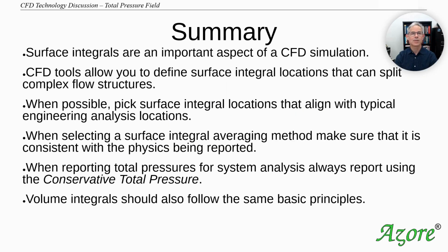So in summary, surface integrals are an important aspect of CFD simulations, but we need to make sure that we use the appropriate surface integral for the appropriate quantity that we're extracting. CFD tools allow you to define surface integration locations that can split complex flow structures.